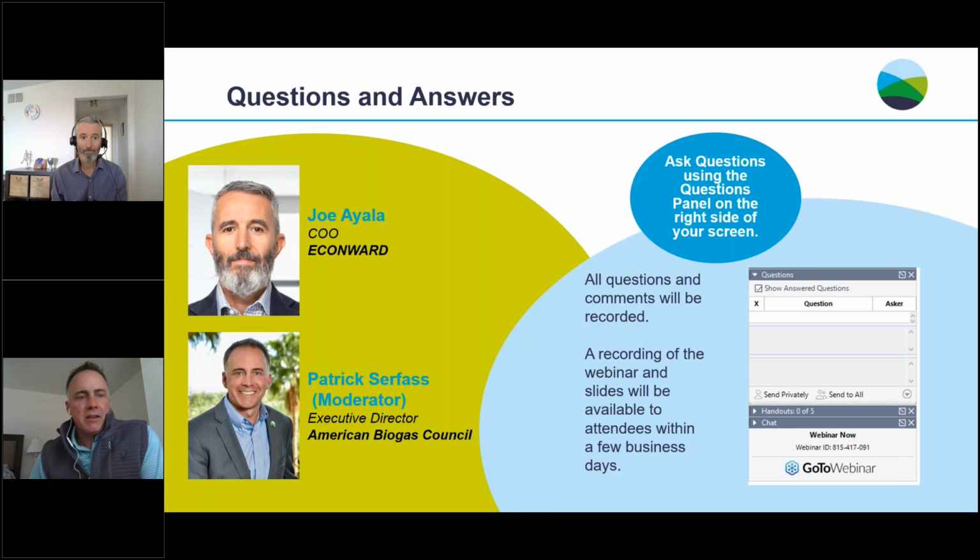I guess I misspoke on the oxygen part of it. The question was regarding whether there is an oxygen concentration within the reactor, the thermal hydrolysis reactor. I mean, it's an autoclaving system. The autoclaving system is not an anaerobic reactor. It's just a pre-treatment. So there's no oxygen added, right? It's just natural air coming in with the material and pressurizing it.